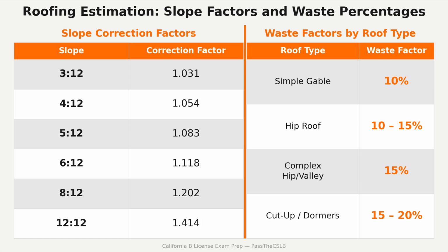At a gable end, wind-driven rain pushes sideways across the edge. Without the drip edge clamping the underlayment down against the deck, wind gets under the exposed edge and lifts it. Water follows the wind under. Memory anchor: eave under, rake over.